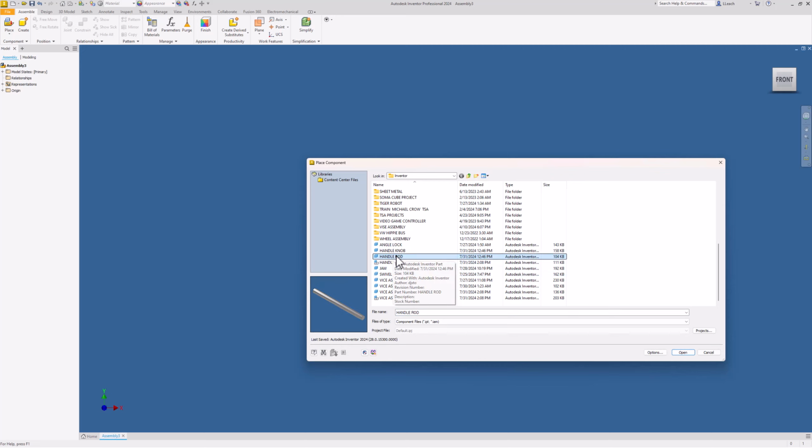So what I can do is constrain just the axis. So I think I used a mate, so I'm just going to pick this axis here and pick the axis, not that one, but the one that goes through that hole right there. Not this one, but this one. Hit apply. So notice it didn't go through it, but it's in the same angle that we need. So now what I want to do is, actually that plane that I have shown is not the one that I want.